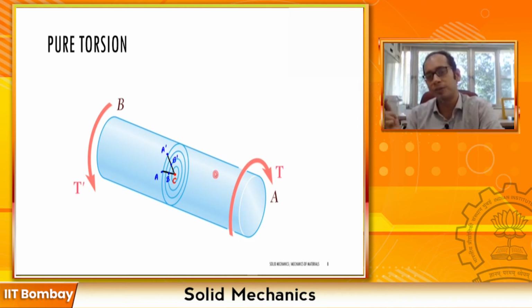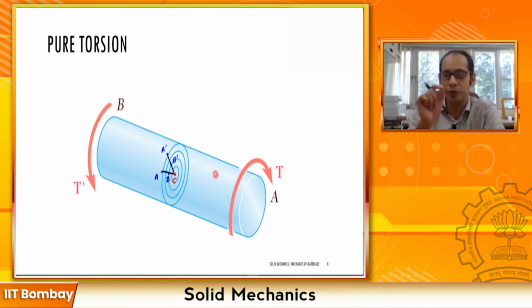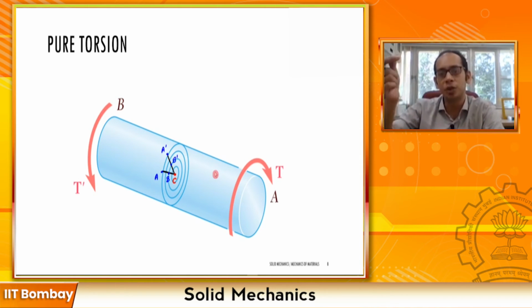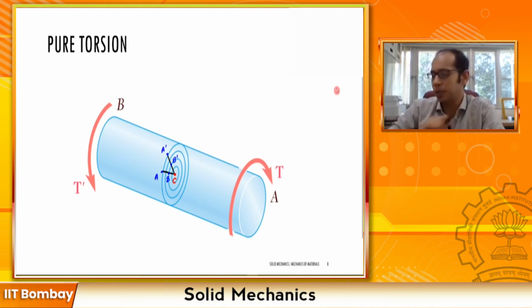So as you are moving further and further away from the center, you are going to have higher and higher amounts of displacement, but again along the same circumferential line. You are not having any warping, the points are not moving to the left or right, it is simply shifting to the top or to the bottom over here. And the displacement of these points keeps on reducing as you are approaching from the outside periphery to the inside point over here, right? So let me poke your memory slightly, or poke your knowledge of stresses and strains at this point pertaining to this topic of torsion.